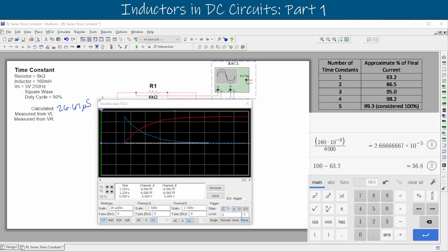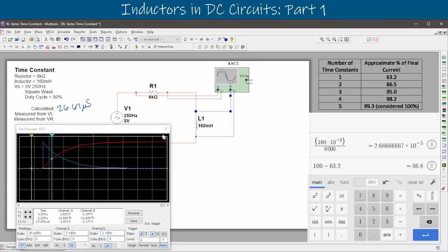And so now that we have seen the voltage on the oscilloscope, we can measure it using our meters here. So we pull these two out. We're given 2 of them. If you click on them, you see this triangle gets bigger on one. You click on the other one, the triangle gets bigger on the other one. So when we pull this out, we see that it actually follows the red line right now, and we actually want it to follow the inductor because we're trying to measure the voltage drop across the inductor, and we know that we made the inductor the blue line.